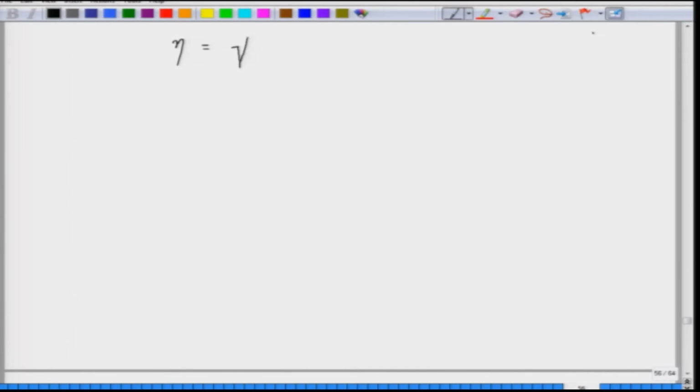We will take two different cases, and before we actually go to that, let me remind you that eta of any medium, which is given by square root of mu by epsilon, in our course would be equal to square root of mu naught divided by epsilon naught epsilon r. And we have already said that square root of mu naught by epsilon naught is basically the free space impedance eta 0, which has a value of approximately 377 ohms, divided by square root of epsilon r.